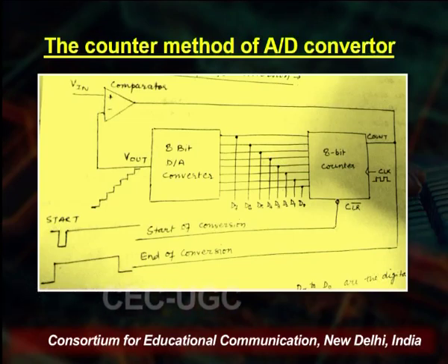As you can see from the figure, we have the AD converter. This AD converter has an analog component. At the top left we have an operational amplifier which is configured in open loop configuration. The moment we see an op amp in open loop configuration, we understand that it is designed to work in the saturation region. So, the output would be either plus saturation or minus saturation.